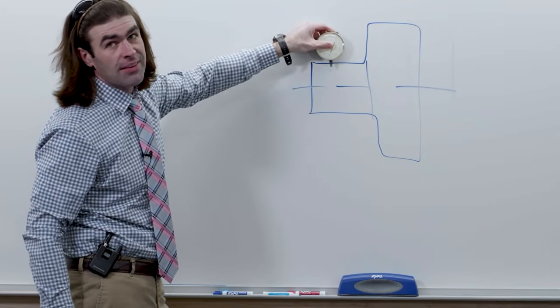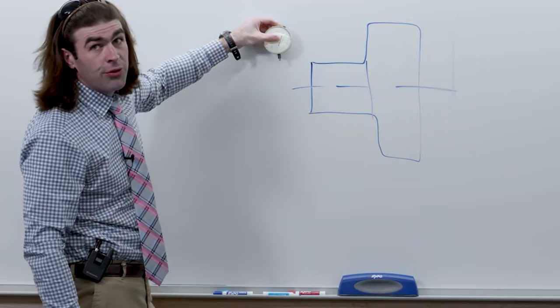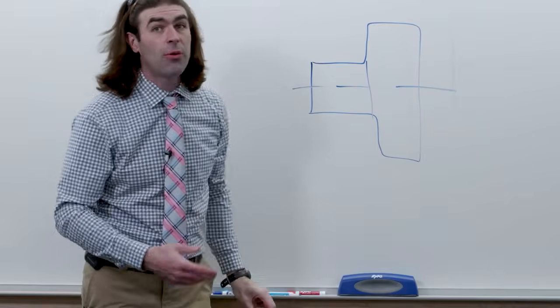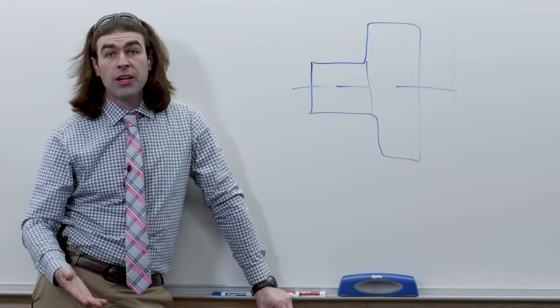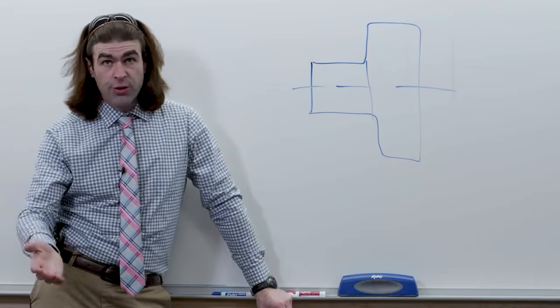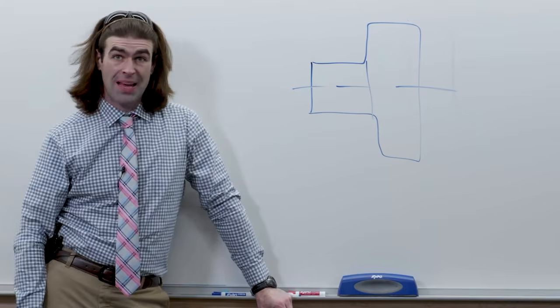It has to stay locked. It can only move in translation parallel to the datum axis. This is how we control the straightness and cylindricity of that feature. So it's a much more difficult tolerance to inspect and potentially to make.